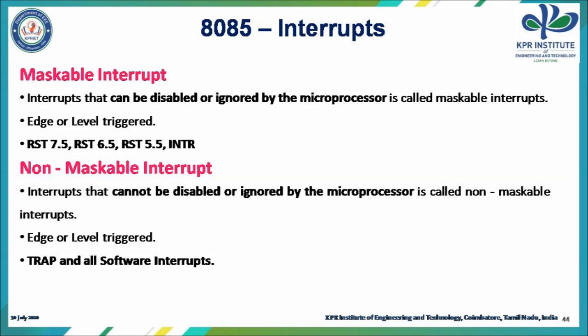Non-maskable interrupts are the interrupts that cannot be disabled by the microprocessor. They can also be edge or level triggered. The only non-maskable hardware interrupt is TRAP, and all the software interrupts are non-maskable interrupts.